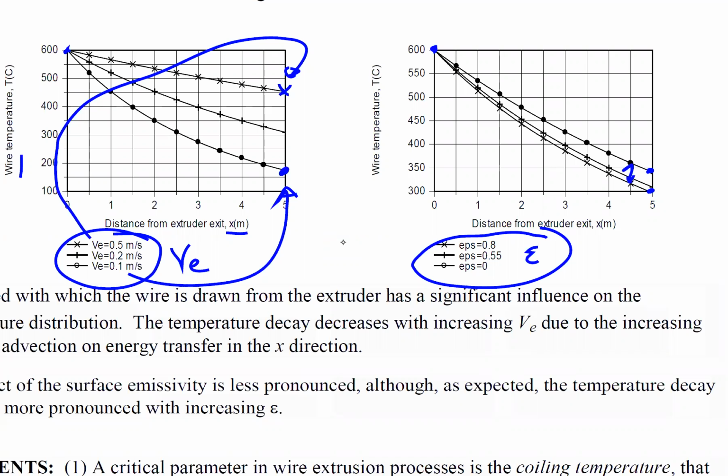So the distance, maybe you instead make this way longer of a distance that you're having it extrude outside of it to help with the cooling process for wire before spooling it, versus shorter distance but lower velocity, because you want that production rate to be as high as possible. Or maybe you look at the convection coefficient and try to put velocity of cross flow higher, okay? Because you want, again, production to be higher, not necessarily just changing the parameter that made it work, because the company's goal is production. So maybe you want to go a different route. Okay.